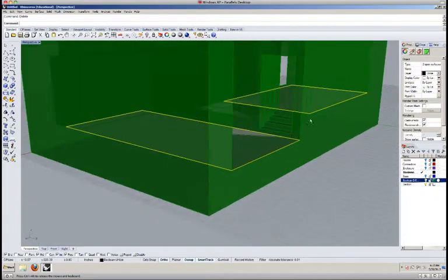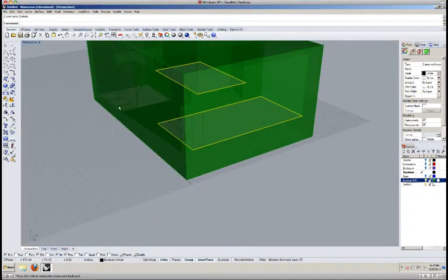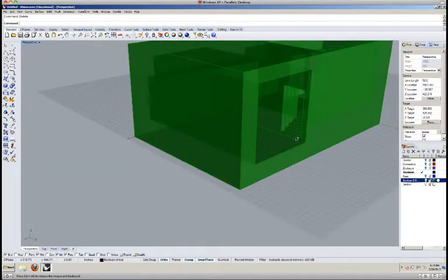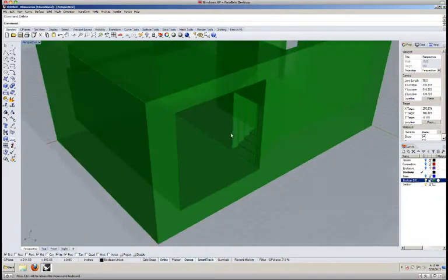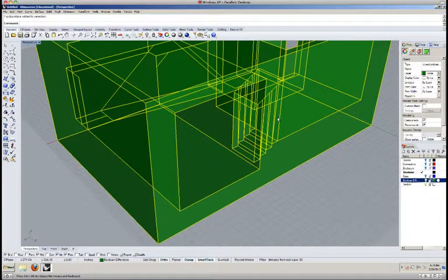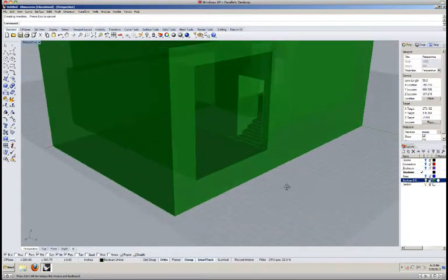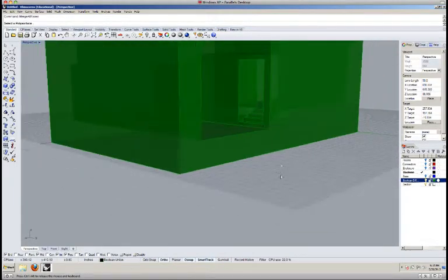And I've got some extra surfaces here on the Boolean union layer that were left over from the construction of copying everything in place. So I'm just going to select these and get rid of them. Or I can turn off the Boolean union layer. That's what that weird interference pattern was doing. You can see here that I didn't simplify the faces for this, so I'm seeing those construction lines. I can do the whole thing. So merge all faces. And it should just clean up the geometry a bit. And that'll help too when we're using the make2d command.